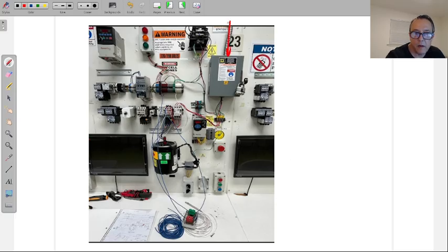This is coming from a breaker, by the way. The breaker is somewhere, there's a panel somewhere that's feeding power into this. So I have power coming into here. I have my fuses in here. They're going to a terminal block because we do like to do that just to make things accessible, right? What this allows is for me to be able to test here, not have to deal with the disconnect.